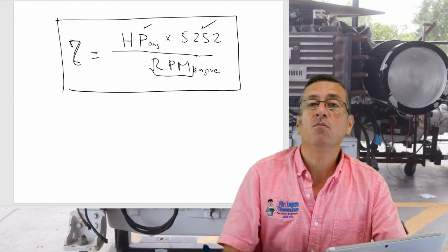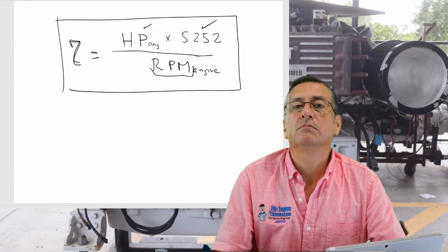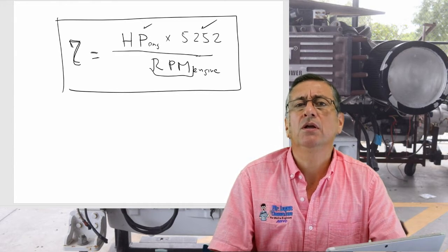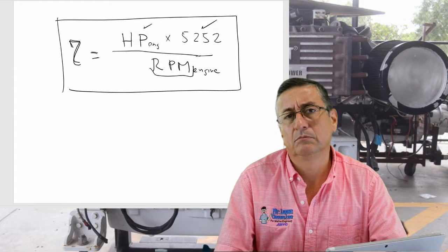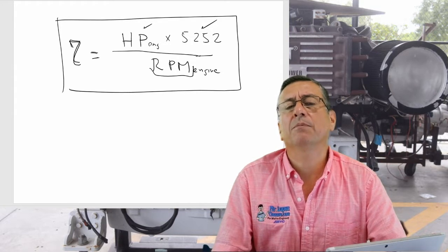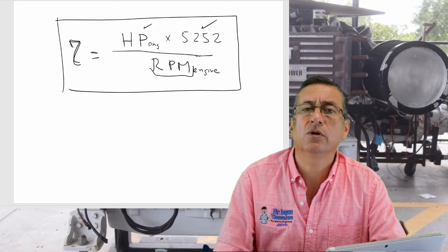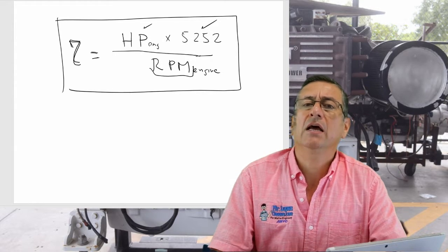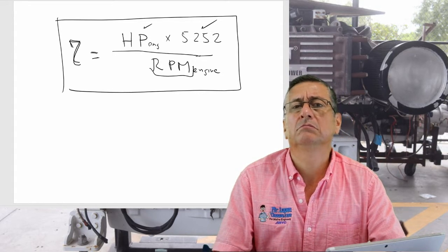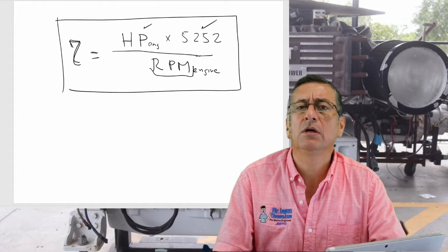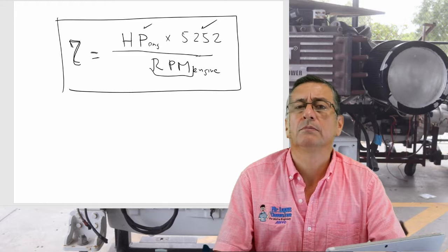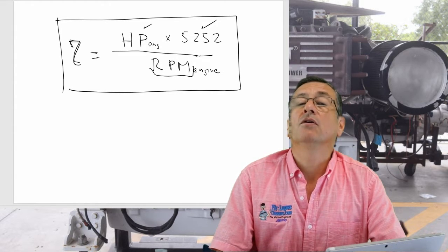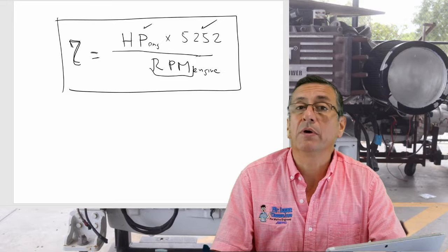It is between 2200 and 2500 RPMs. This is the maximum RPMs in a typical inboard diesel engine. And what is the idle? The RPMs at idle is normally around 900 RPMs, right? Don't forget, keep in mind that number.